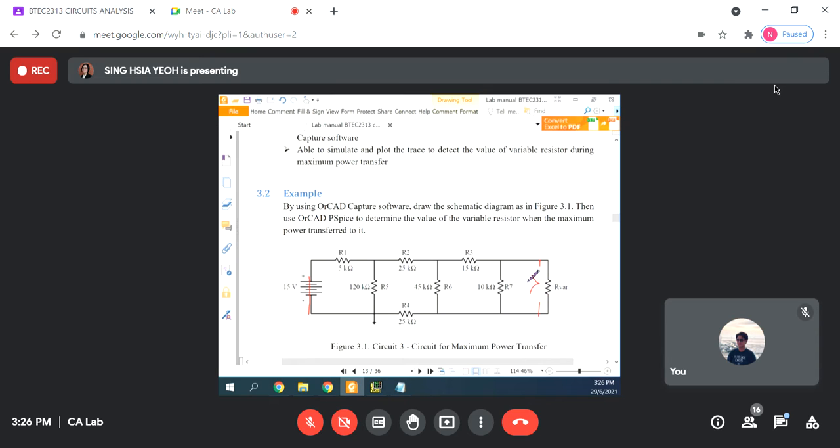Okay, you need to look inside here. So this one and two will be in parallel, series, parallel, series, and parallel. Can you then tell me what is your RTH? For maximum power transfer across the resistor, the theory stated that you need to have the Thevenin resistance. So you need to look inside here and find the Thevenin resistance. In 5 minutes, let me know what the answer is.